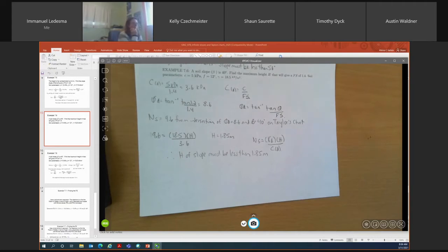So in the real world, when would you assume that you have an internal friction angle of 0? You sometimes do it when you're doing modeling for excavations. So we'll use Taylor's charts or undrained shear strength when we're going to determine what the short-term stability of an excavation would be. Primarily when we're doing our modeling in the more complex modeling programs, we'll assume a friction angle and a cohesion. So it's more so when you're doing temporary stability of excavations, you'll use an undrained shear strength value.